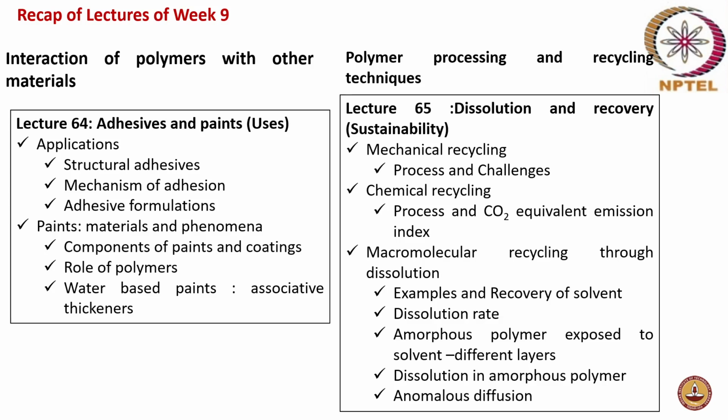Next, the topic shifted from interaction of polymers with other materials to polymer processing and recycling technique. Okay, and lecture 65 was on dissolution and recovery. So this was on sustainability aspect. So mechanical recycling, the process and challenges in mechanical recycling, and then what is chemical recycling, and what are the process, and what is the CO2 equivalent emission for different chemical recycling process were discussed in detail, and of which this dissolution phenomena had very low CO2 equivalent emission, which is a very, very promising aspect, right, for recycling of polymers.